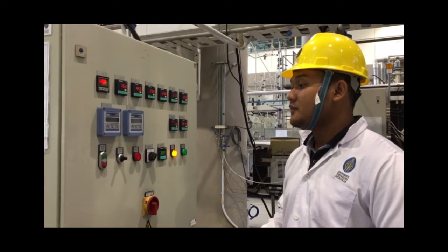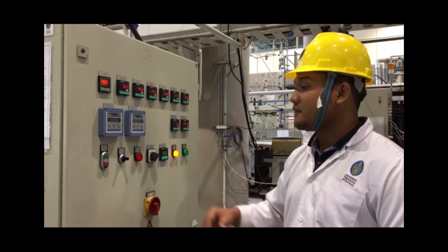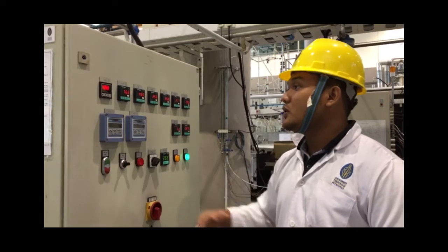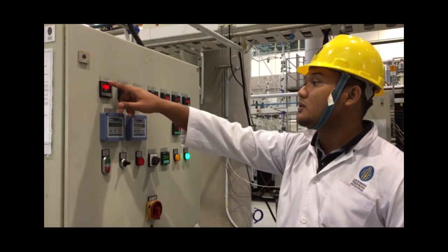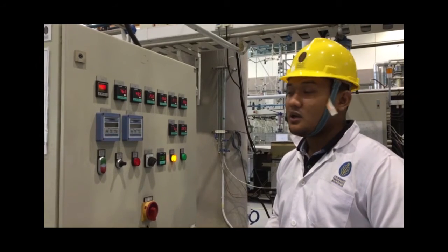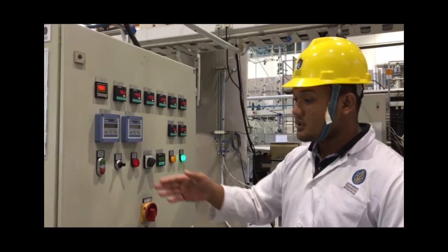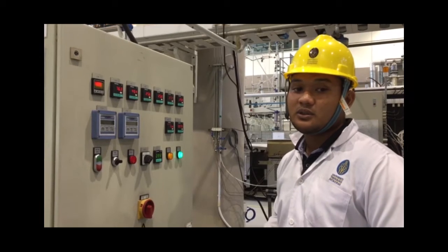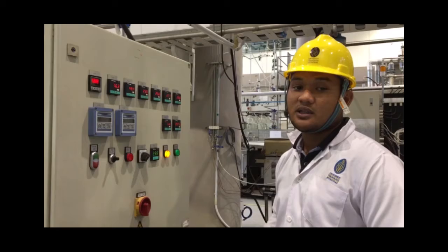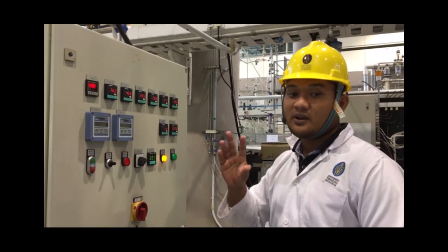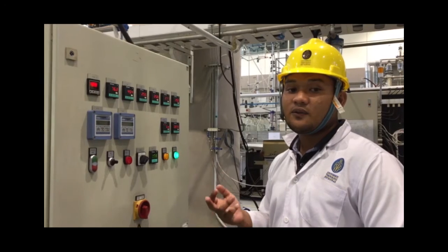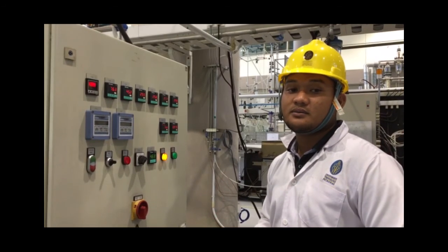For example, for the first heating power, after we set the heating power to 70%, we wait until the T101 and T102 temperature stable. After that, we take the sample of the distillate and bottom, and then we can change the heating power to the next heating power, with 5 different heating powers, which are 20, 40, 80 and 100.